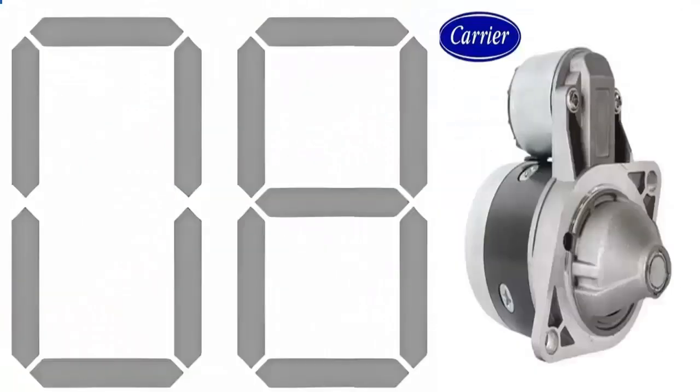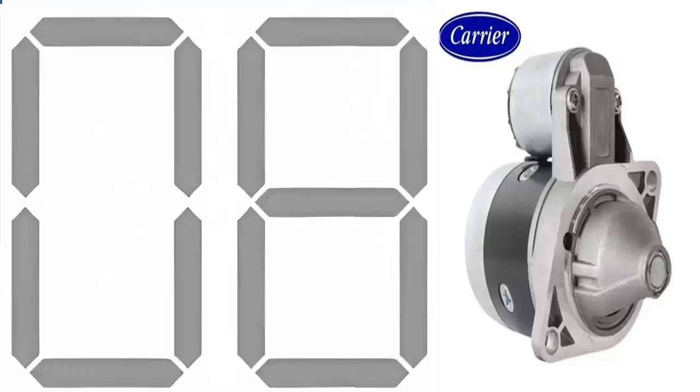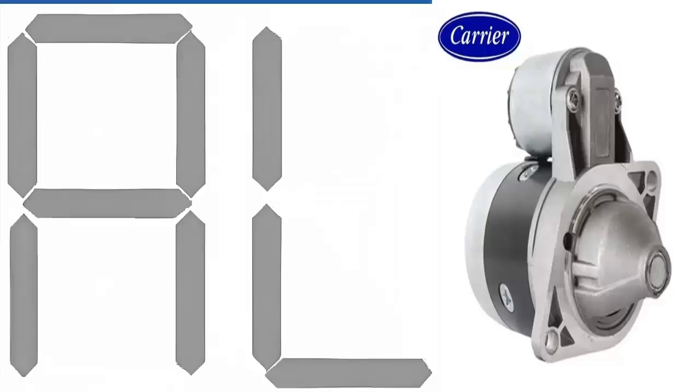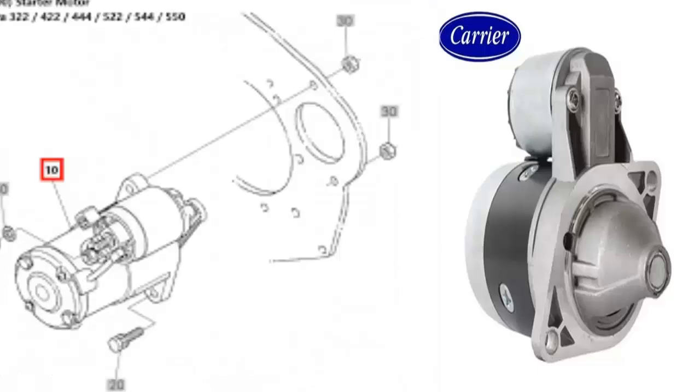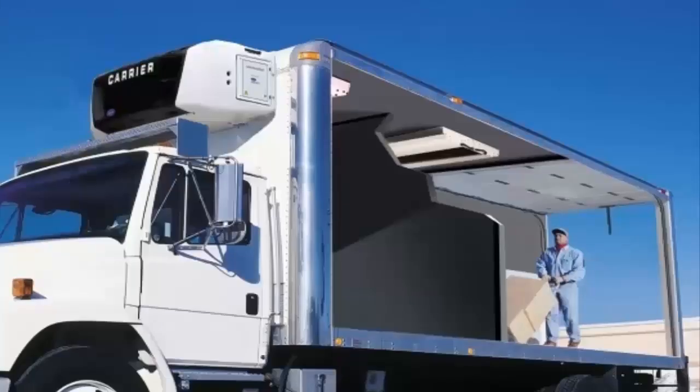9. Diesel engine starter signal not detected. This fault is identified with code AL8 and may be due to solenoid or electrical connection failures. It is recommended to check the starter solenoid and its wiring.